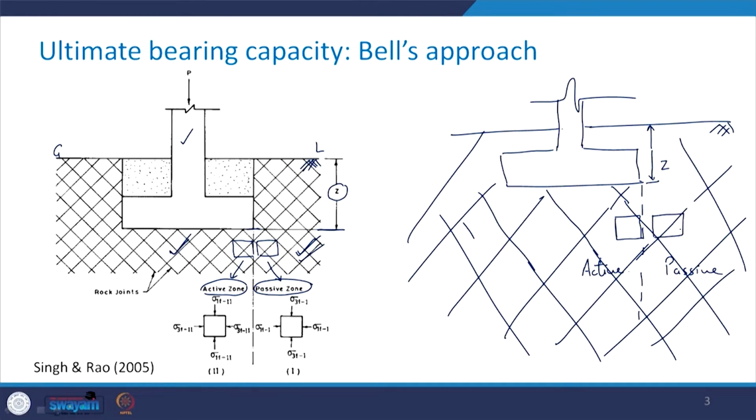This is just below the footing. So, what is going to be the value of sigma 3 here? That is going to be gamma times z, where gamma is the unit weight. Although for clarity I am drawing it a little bit below, this element is just adjacent at this particular level only. And here we have sigma 1. Likewise, here you will have sigma 3, and for this element you will have sigma 1.